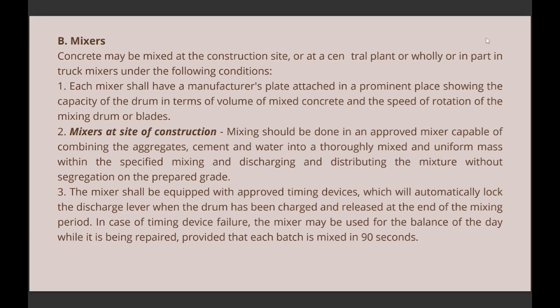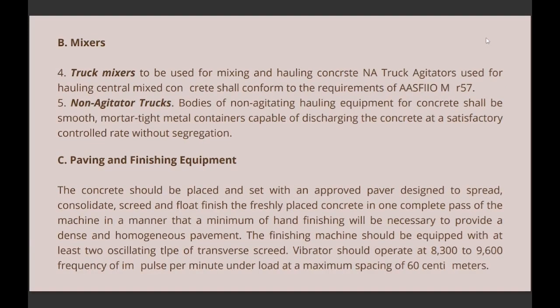And number three, the mixer shall be equipped with approved timing devices, which will automatically lock the discharge lever when the drum has been charged and release it at the end of the mixing period. In case of timing device failure, the mixer may be used for the balance of the day while it is being repaired, provided that each batch is mixed for 90 seconds.